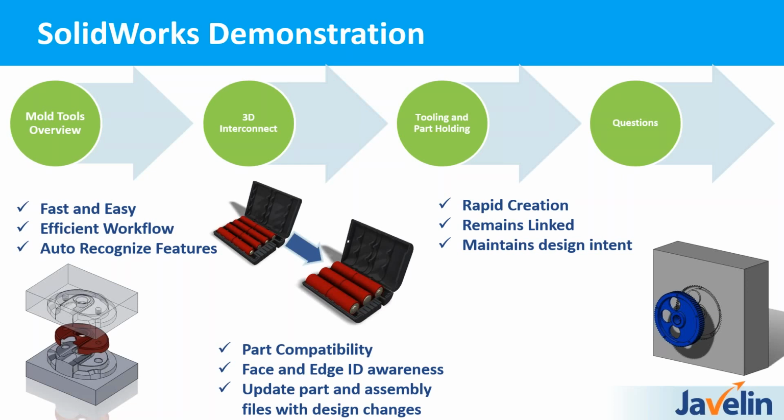Any method you could use in Windows Explorer or with SOLIDWORKS to open an existing file, you can open with 3D Interconnect. It opens as if it was the native data, and you can run further import options if you wanted to do some feature recognition on that. At that point, you have that option, or you can just use that part as it's been supplied to you. Does that answer your question there?